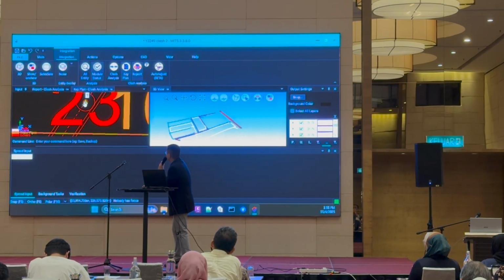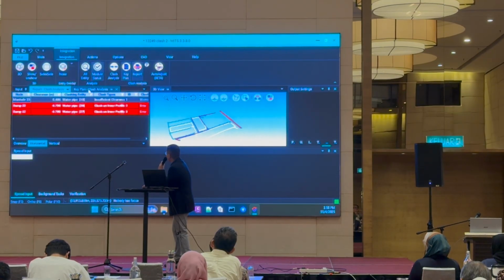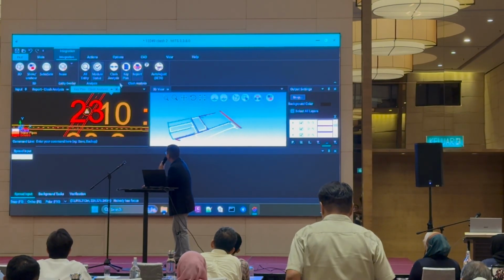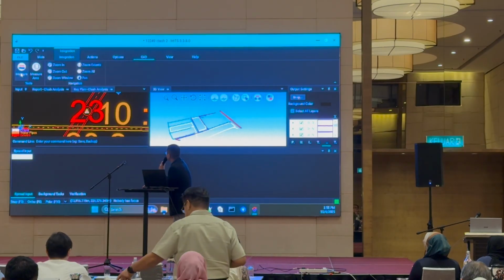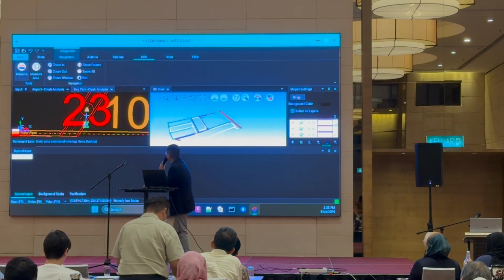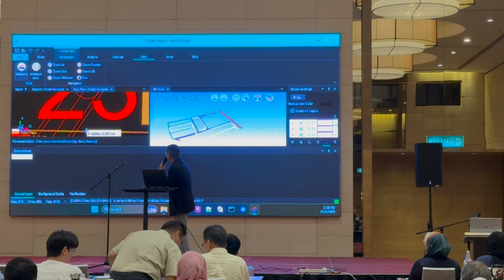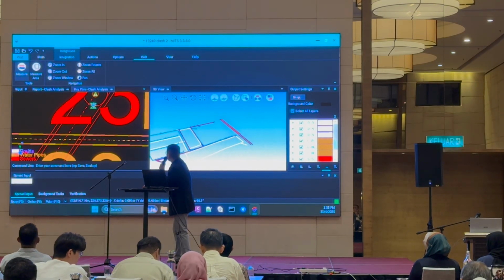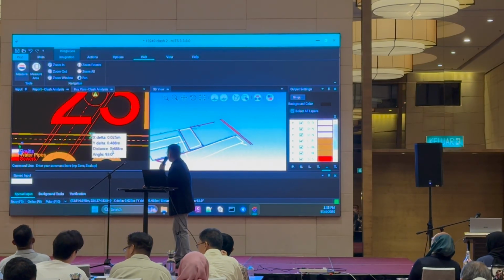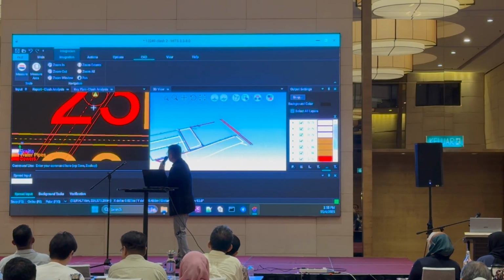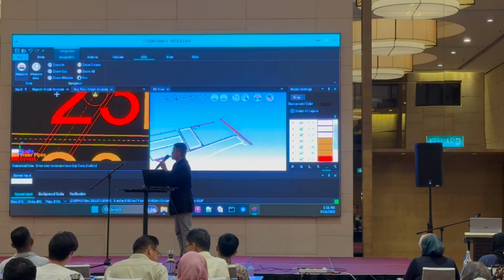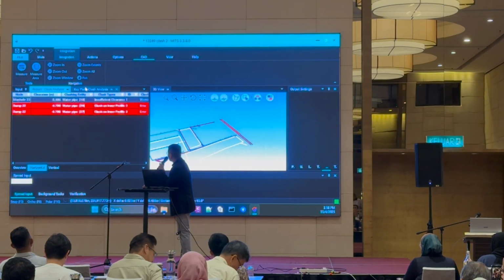This is our entity here, a manhole, and it clashes with the water pipe. So we measure the water pipe and the manhole. Let's try to measure. You go to CAD, measure, and we take the point. Oops, we cannot see. Too bad. We just measure again. 0.488, about there, because maybe my hands are not precise enough to get the minimum distance. But you can verify, to satisfy your curiosity, that they are consistent.